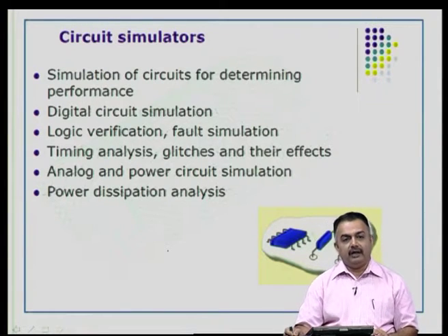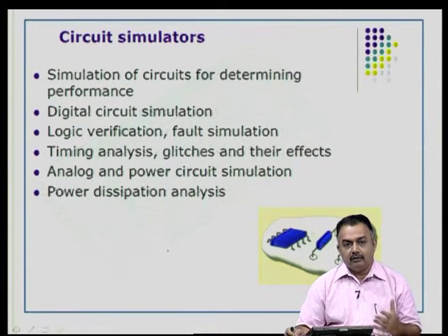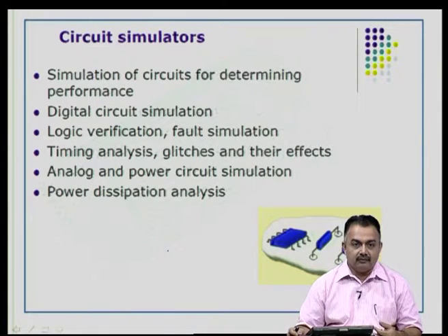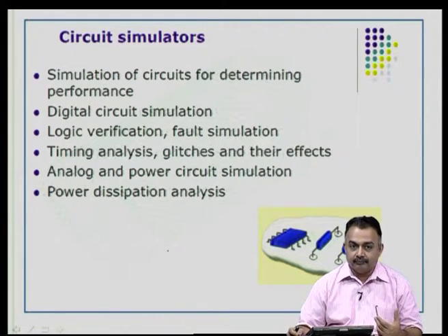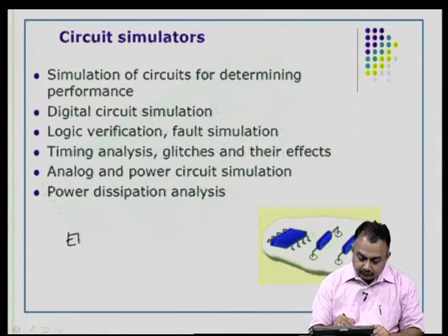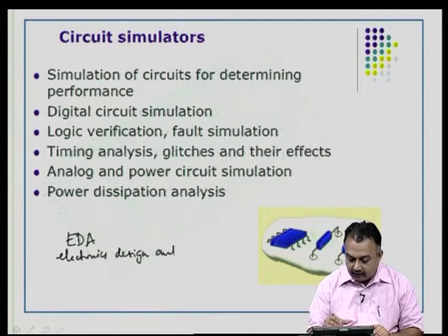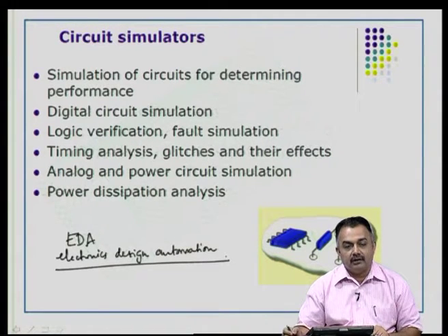Some CAD software will have circuit simulators. Low end software will not have simulators, but you can work with low end software and utilize those schematic and netlist information as input to another high end software which will have a simulator. Okay. So, in case your CAD program or your EDA tool, electronic design automation tool, that is the term used for CAD programs which contain all the aspects of printed circuit board design.